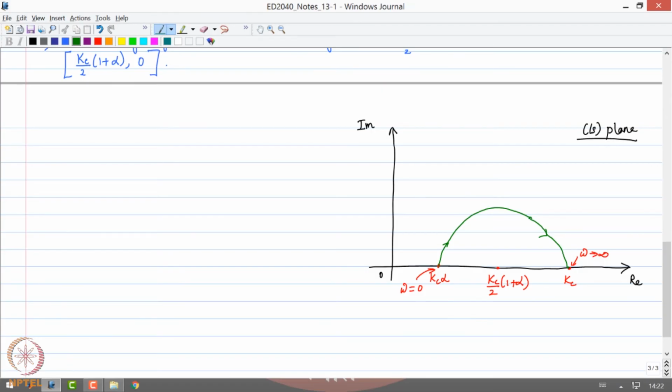And the maximum phase angle which can be obtained from this particular transfer function can be figured out by drawing a tangent from the origin to this semicircle. If we look at this line segment, the length of the line segment is going to be the radius of this particular semicircle. So, now let us call this angle phi m.